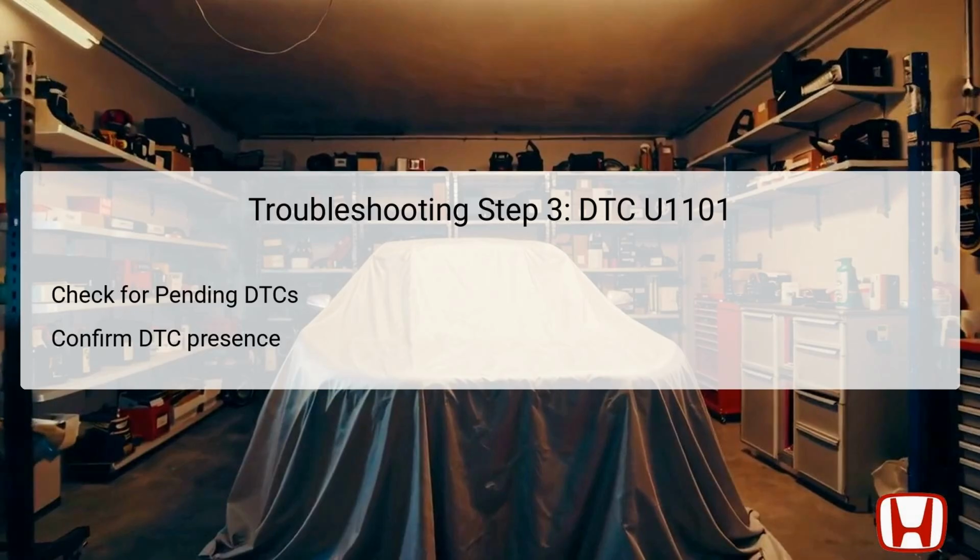Conversely, if no issues are confirmed, it may reflect an intermittent fault in the system, suggesting that the circuit connections may need inspection for poor contact or loose terminals. Recognizing the difference between the two will inform the technician on how to proceed effectively.